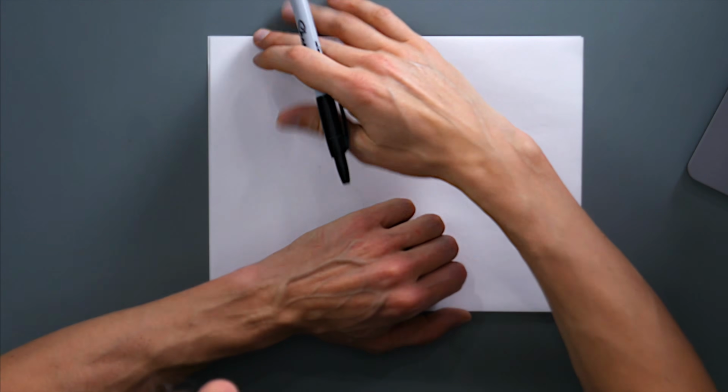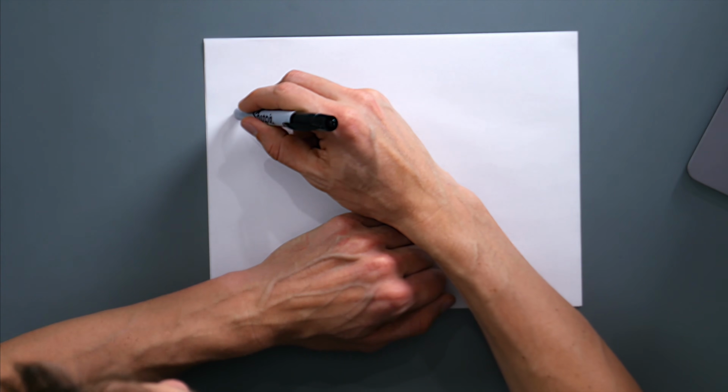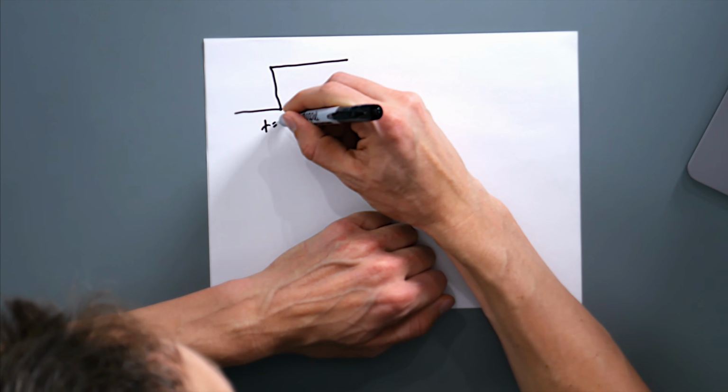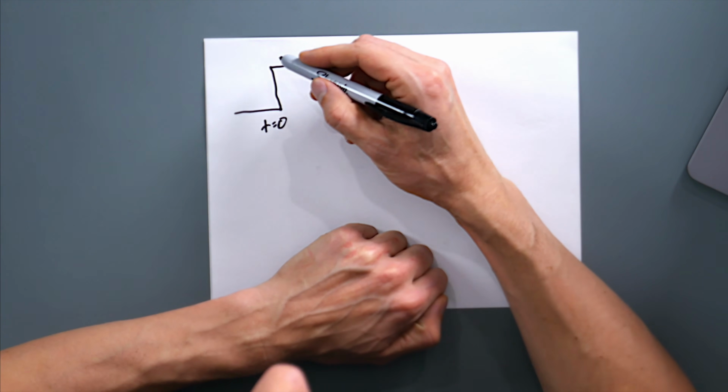But at the same time, despite the world being very, very random, you can actually kind of simulate most inputs with just 4 inputs. And those are the 4 inputs that we are going to go over. So these are the things that typically happen to any system anywhere. So now, I get to break out my Sharpie. The first input that we typically see, and it's extremely common everywhere, is the step input. And so that is where at time equals 0, you go from 0 to 1.